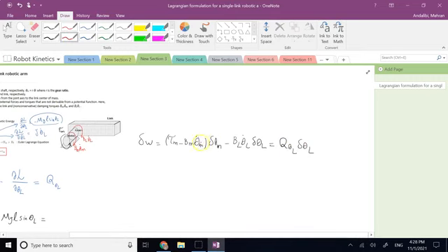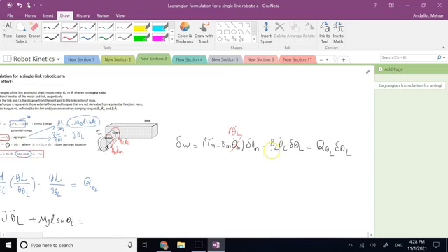All I need to do is replace this theta dot m by r times theta dot L, and the variation delta theta m by r times variation delta theta L. And they both come really from the initial definition of theta m is r times theta L. Because if you take the time derivative from it, you get the first relation that we used. And if you take a variation from it, then you will get the second one that we used.